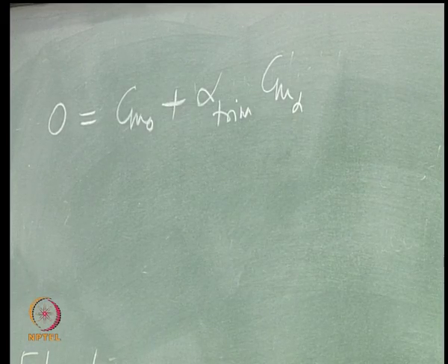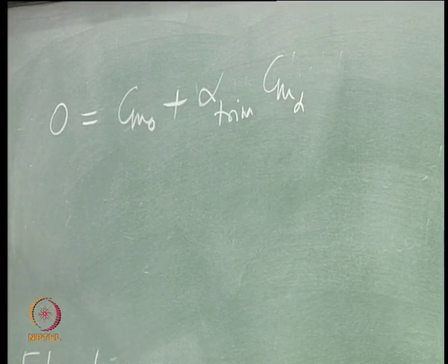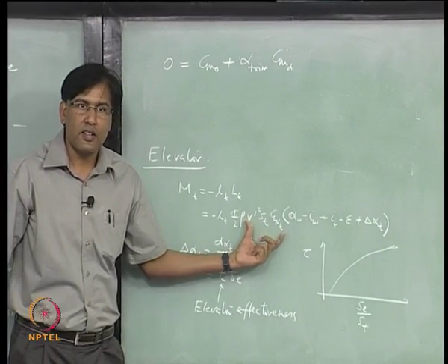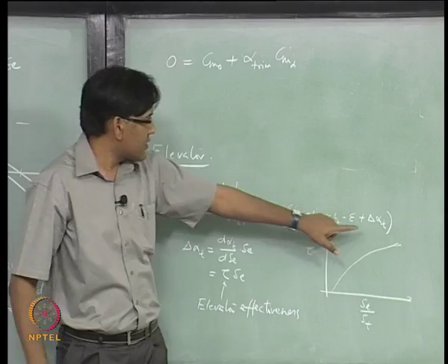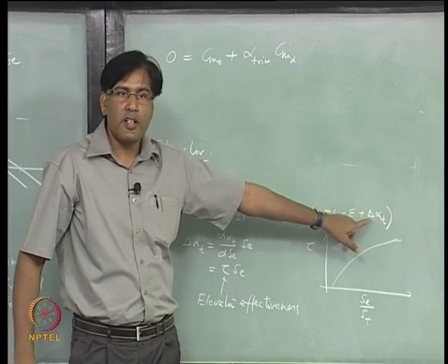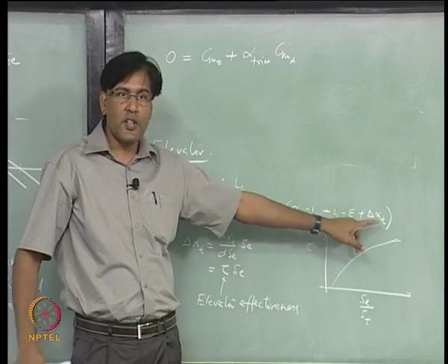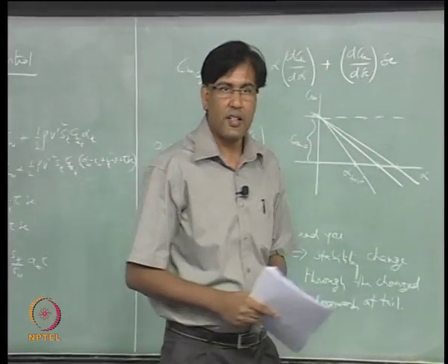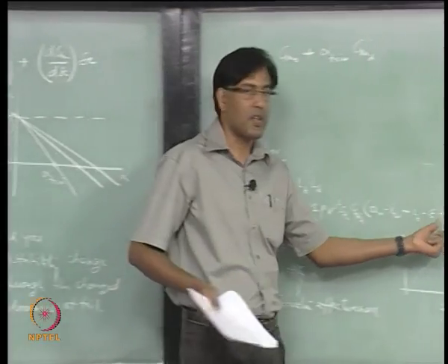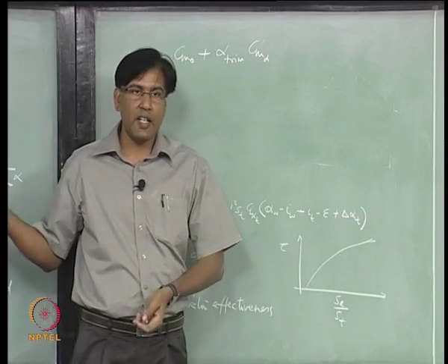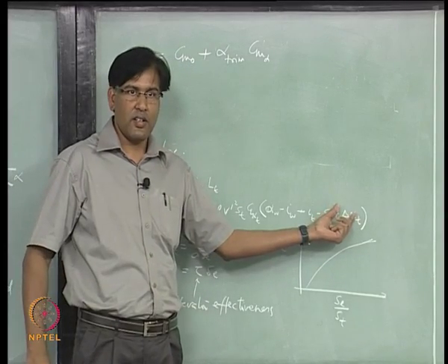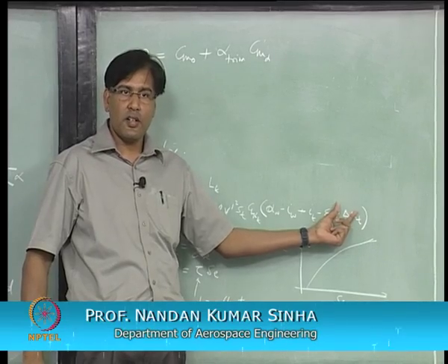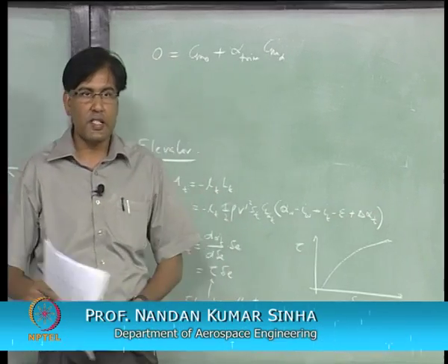Do you see that? For stability we had to take the derivative of this with respect to angle of attack, isn't it? This quantity is not going to change, it is only going to change when you apply elevator, right. It is not going to be dependent upon the angle of attack that the aircraft is going to see, isn't it? So, this is not going to affect the stability of the aircraft,